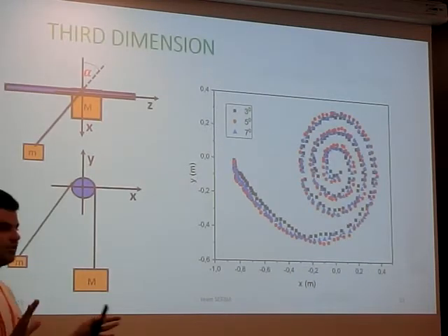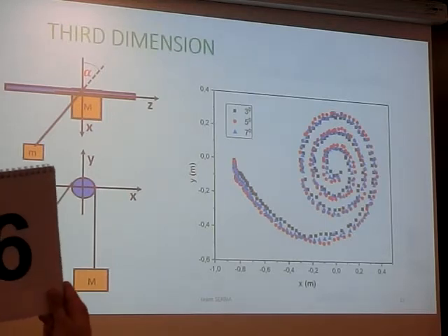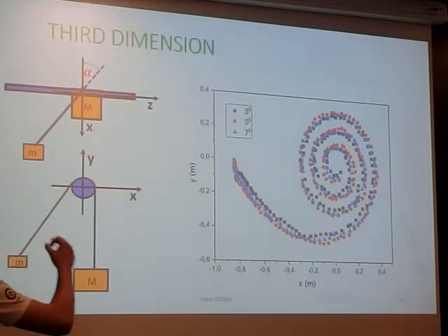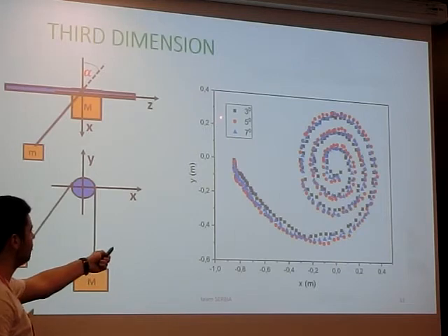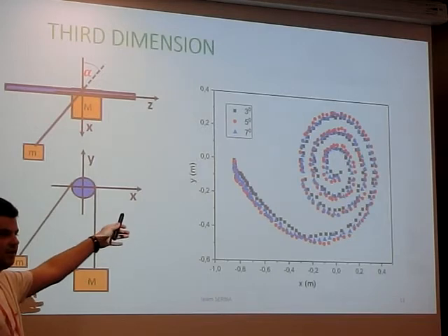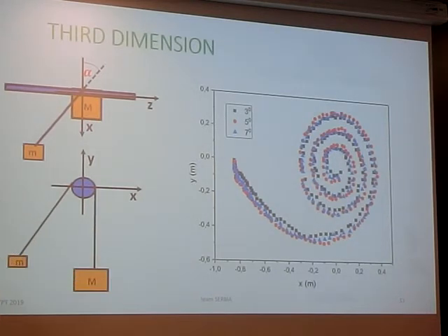Our simulation is just a 2D model, but in reality we don't have a 2D problem, because if we release the rods in a 2D plane, they will hit each other. So we need some small angle alpha to avoid the rods colliding. To see whether a small angle alpha, the azimuthal angle, has any influence on the trajectory, we recorded trajectories for 3, 5, and 7 degrees. We concluded that there are no big differences in trajectory for those angles, so our simulation is just a 2D model.